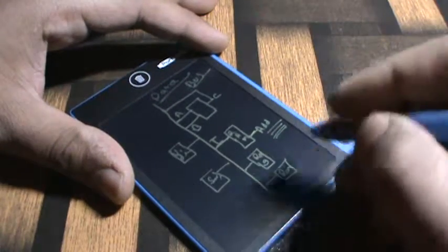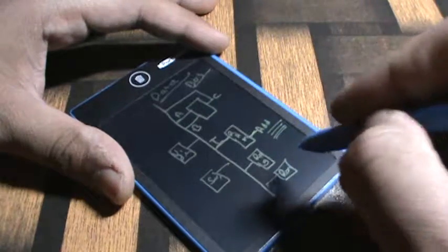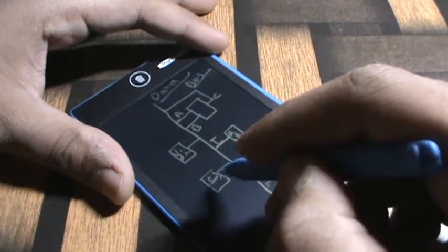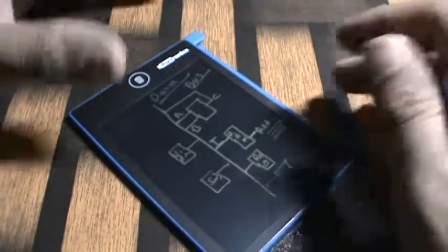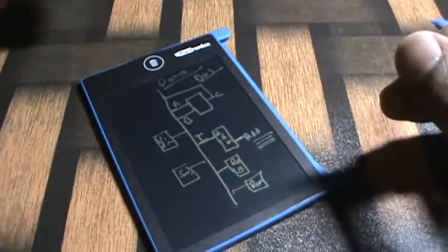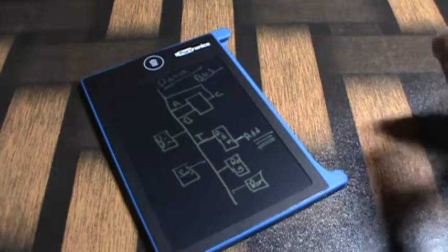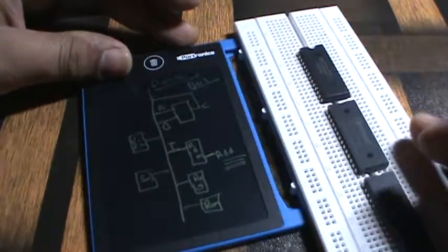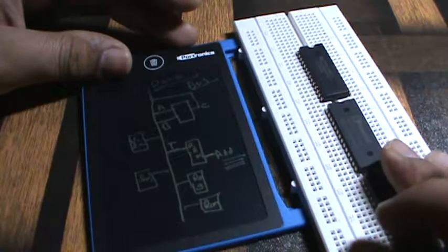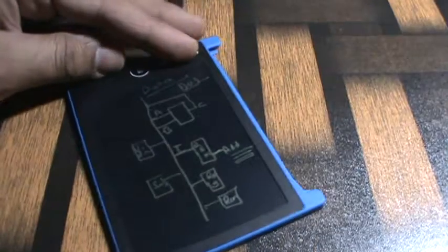So every RAM, ROM, sound chip and everything is connected to an address bus as well. The address bus is going to define which chip needs to be activated, and whatever I'm telling you is going to be a part of the 6502 computer that we are going to build.